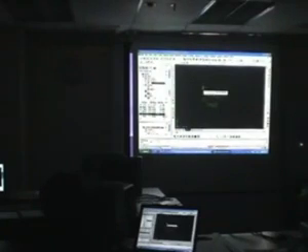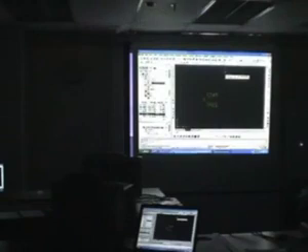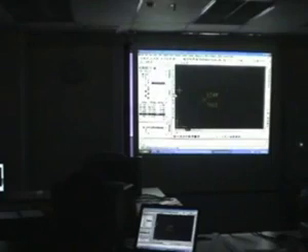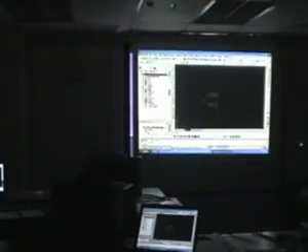Now the bit about contours and the triangles that we want to generate from the surface is very much different from Land Desktop in the sense that we don't have to create it. When we generate contours in Land Desktop, we go to Terrain, create contours, select the attributes and the interval and all that. We don't have to do that here. What we need to do is set the settings in Civil 3D. We still need to specify what the intervals are for our contours, and maybe the colors for your contours, but that falls under settings.